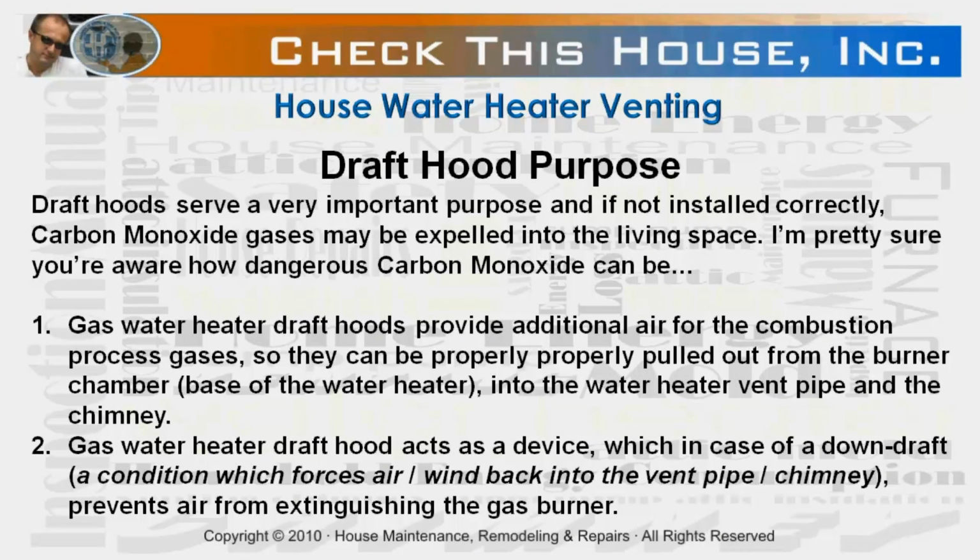There are only three components of the natural draft water heater venting system, so it's really difficult to make a mistake during the assembly, if you know what you're doing, of course. The first of those components is called a draft hood. Draft hoods serve a very important purpose, and if not installed correctly, carbon monoxide gases might be expelled into the living space. I'm pretty sure you are aware how dangerous carbon monoxide can be.